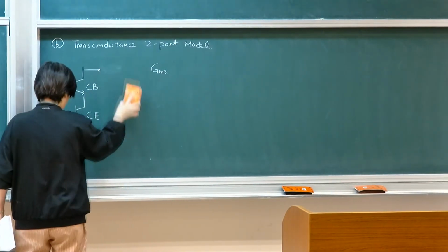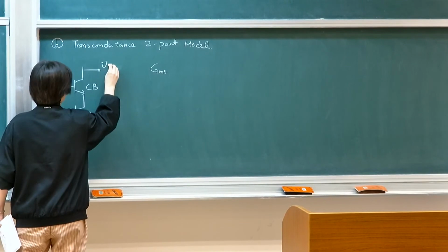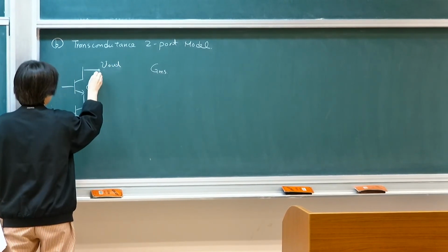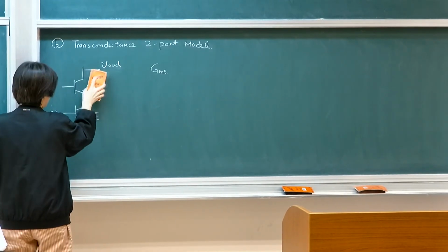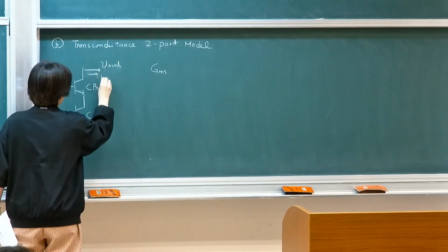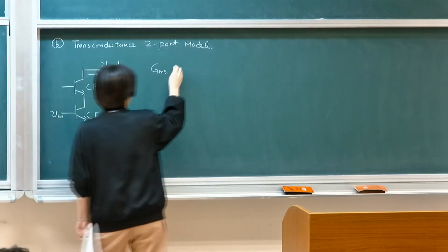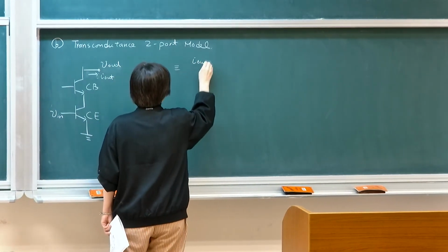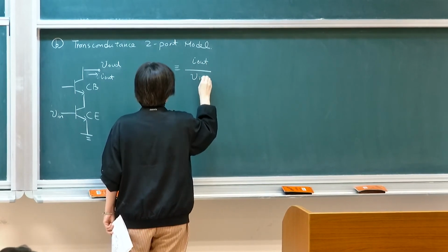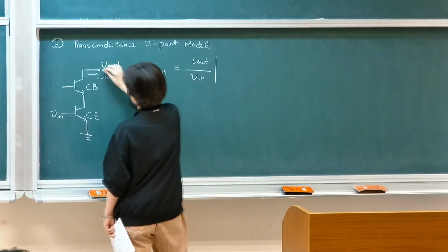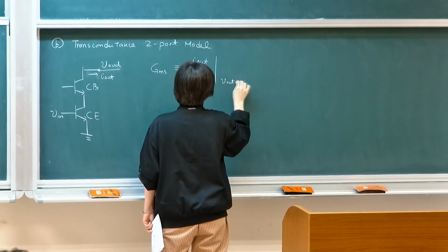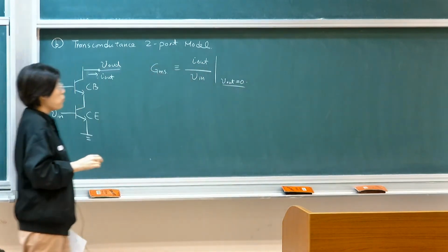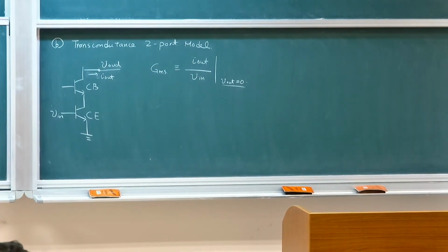So it's basic. For a transconductance amplifier, what you look for is the input voltage, and then we look for this current. You also look for the output current. By definition, this is I out as a function of V in when the output is shorted, so this is when V out equals 0. That stands for output short, where you get the maximum current.